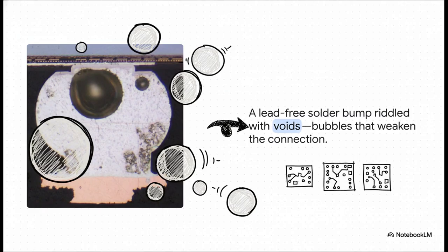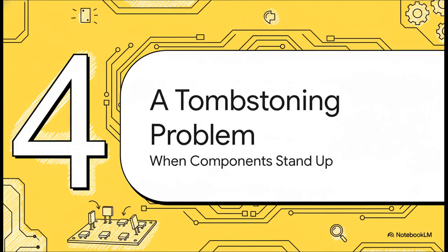Those are voids, pockets of trapped gas that form during that high-temperature soldering. And every single one of those bubbles is a weak point, a potential point of failure that can compromise the entire connection. But that's not the only challenge.